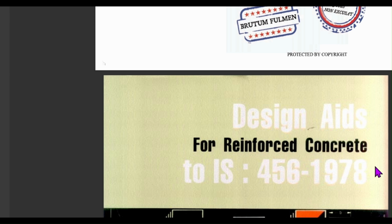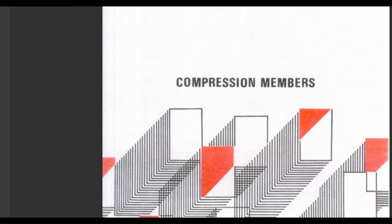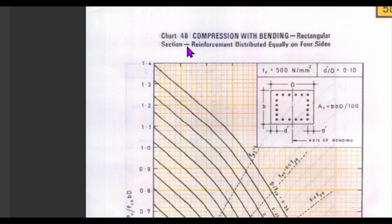There are a lot of charts given to make the calculation so easy. Now in this, first we are going to enter into compression member. Compression member is the column. This is chart number 48, compression member with bending, rectangular. Normally we design this column considering that it has a uniaxial bending moment in xx direction. Then we will go to biaxial bending.